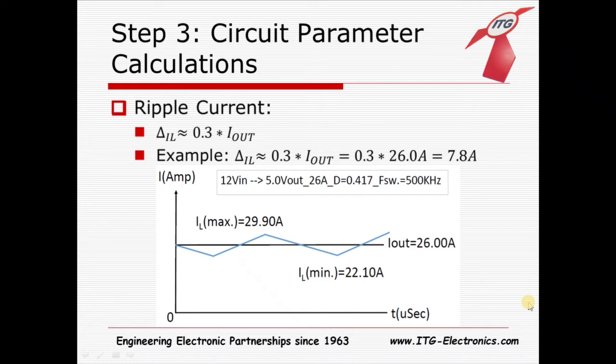The ripple current determines how far above or below we're willing to tolerate as a proportion of our target current. For this example and for general purposes, it's usually around 30%, or 0.3, of the target output current, though that can vary based on your specific application. But 30% is a pretty good rule of thumb.